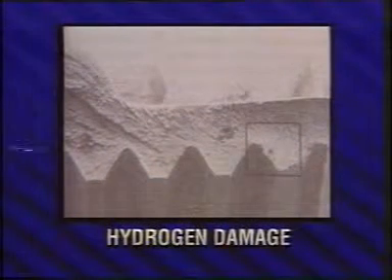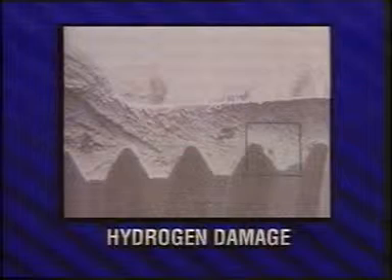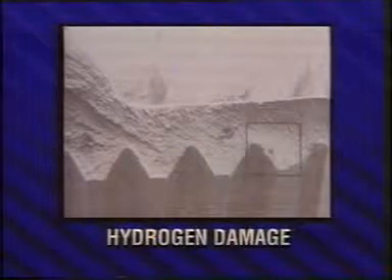Plating is usually detrimental to the fatigue strength of plated parts. Carbon and low alloy steels, particularly steels of high hardness, are susceptible to hydrogen damage. The hydrogen is absorbed during the plating cycle and the associated acid cleaning cycles.